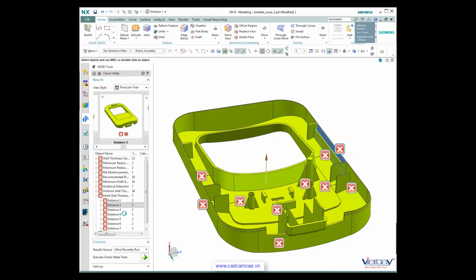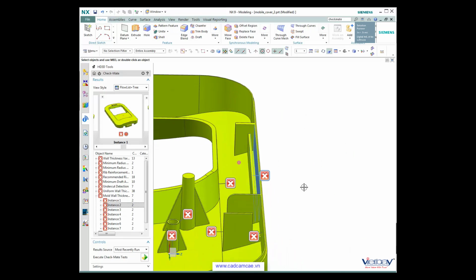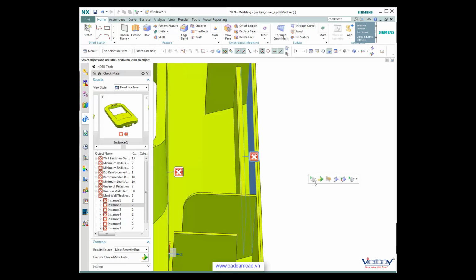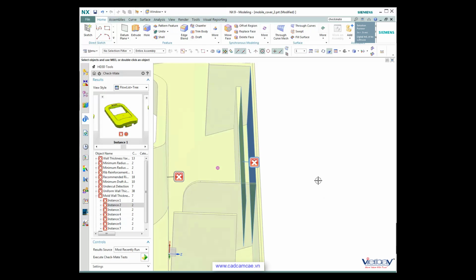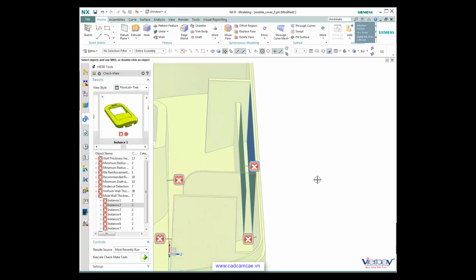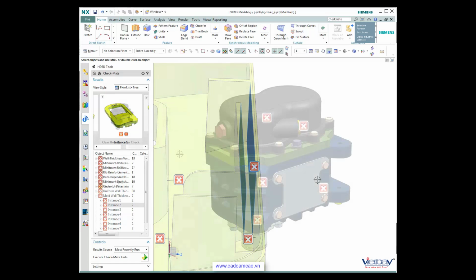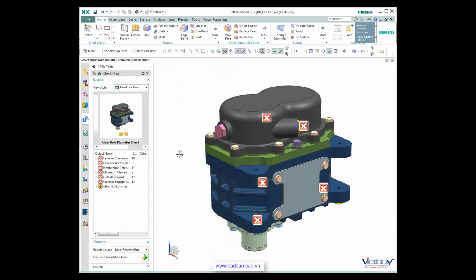In the DFMPro injection molding checks, a thin steel condition is noted when two of the plastic walls are too close together, which in turn affects the tooling where the core and the cavity walls are very thin. This ultimately affects the tool life in the plastic injection molded parts.